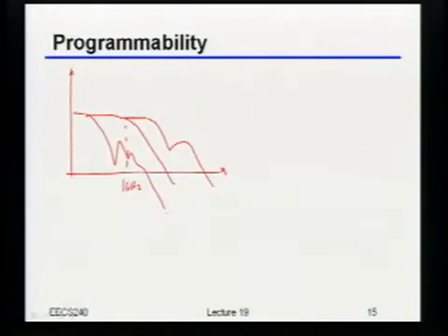What that basically means is we'd really like to have a way to make it so that when we build our equalizer, we can actually tune it, right? We can actually move the locations of the poles and the zeros around, okay? So in order to do that, and I'm just going to draw things conceptually with our active inductor load, but the idea is very similar for the other cases as well. So if we wanted to do something like that, we're going to have to change any one of basically 3 different things, right?